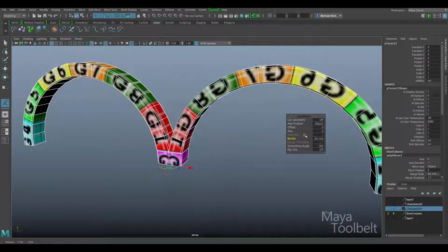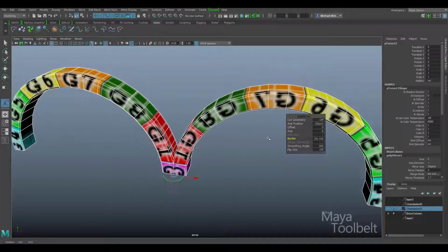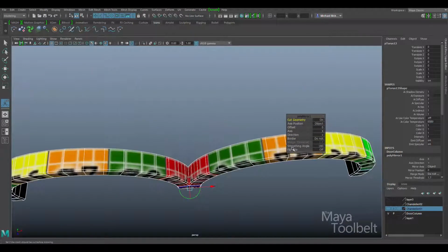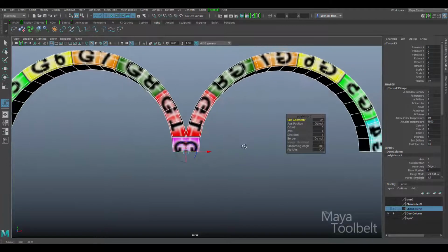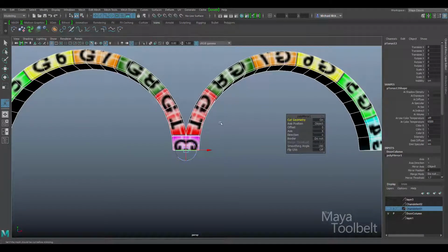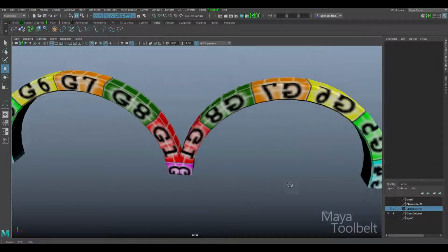Okay, so what I did was make sure it was x-axis and that the axis position was aligned with the object and not the world. Okay, and with that turned on, I could then see, let's see, make sure cut geometry with that on or off. We'll leave it on. Doesn't seem to be hurting anything. Okay, so with axis position set to the object, axis direction is the positive x-axis direction, and we did not merge the border. All right, that seemed to work fine.